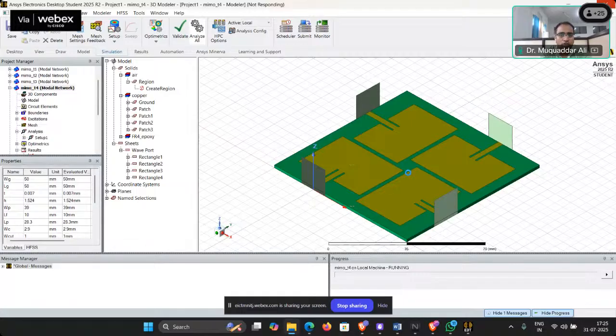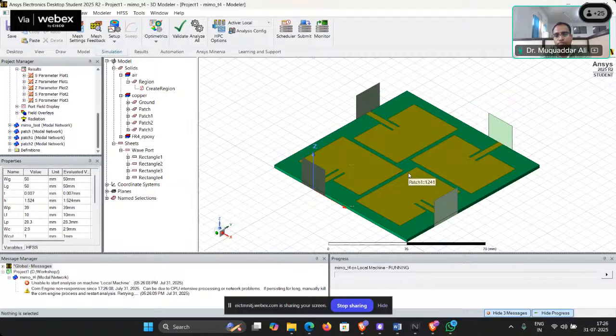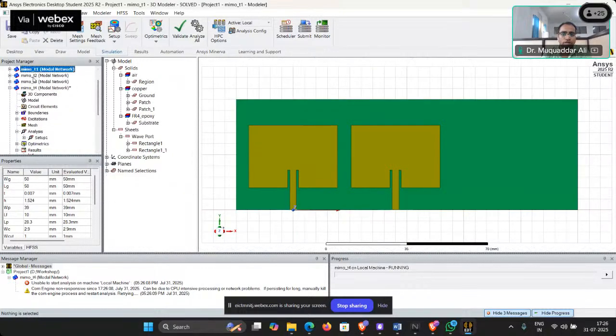So at the receiver side, the polarization should match in order to accept the incoming signal. So there might be some variations. So what we can do, we want to have a fixed polarization. We are not giving polarization diversity. We want to place our antennas like this, not like this.